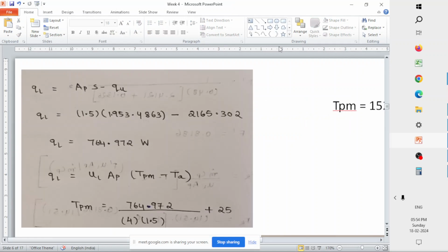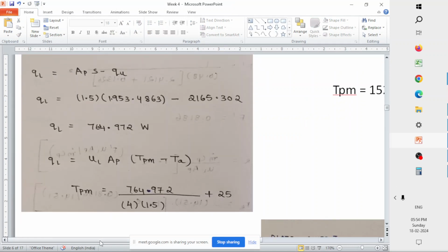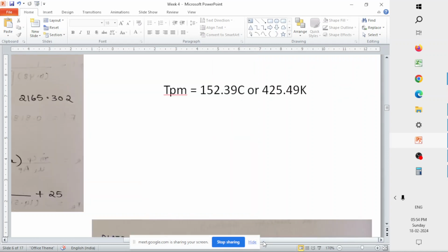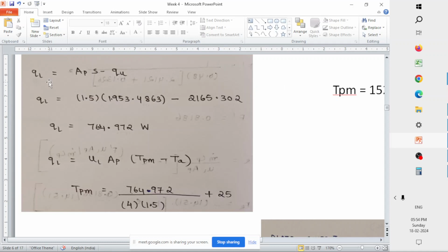So this is the absorber plate mean temperature, that is the mean plate temperature of your absorber plate, in other words. But the main thing is the expression. What does the expression actually mean? The QL is your heat taken up by your absorber plate, which is basically the amount of energy that is absorbed minus the amount of energy that is gained by the fluid.